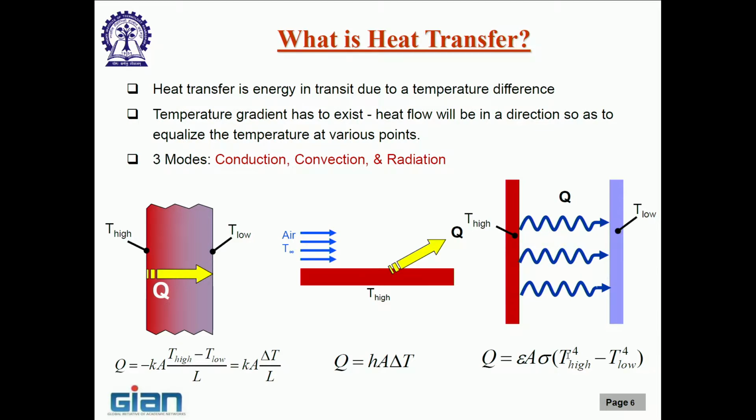Okay. So, many a times we neglect radiation, especially when you have, let us say, convection because of movement of a stream of air or water. We will say the radiation component will be so small and negligible that we are not going to consider that. The primary reason for heat dissipation is going to be either conduction or convection, but that is an engineering judgment we have to take. Many a times if we neglect radiation, it can also lead to underestimation of heat dissipation.